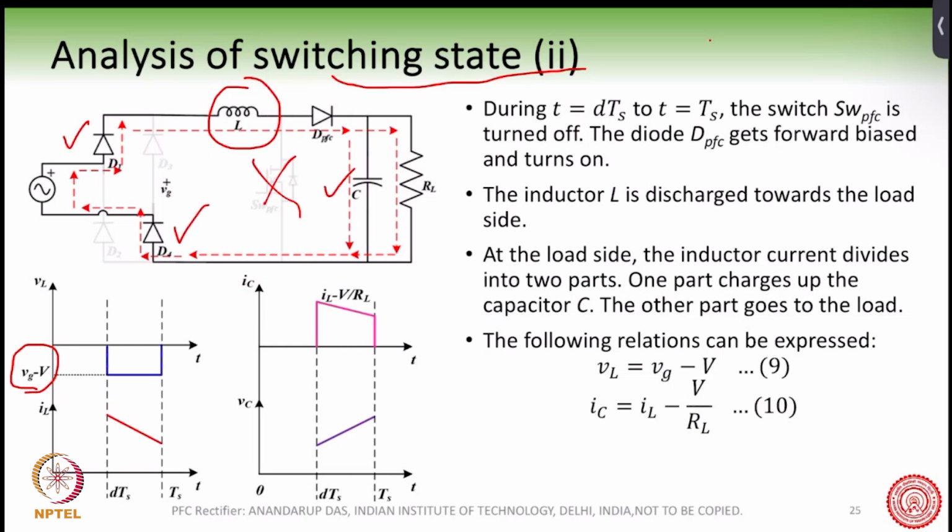Okay. And this also is consistent with what we know as the volt-second principle for the inductor voltage, which we study in the conventional DC-DC converter. So we had given a positive voltage in the first half cycle, and we have given a negative voltage in the second (1 minus D) Ts time period. And so if this voltage comes across the inductor, then we can also write that the inductor current will fall, right? Because now L di/dt is negative, right?